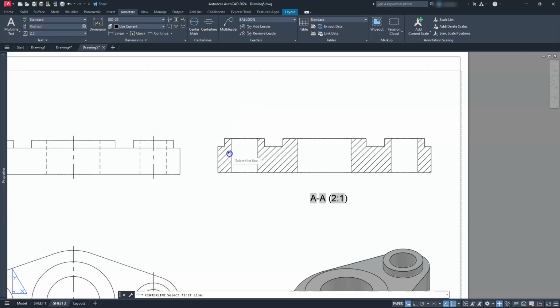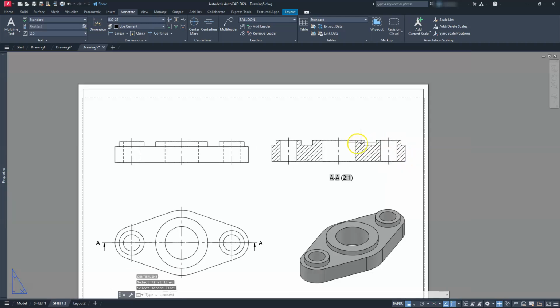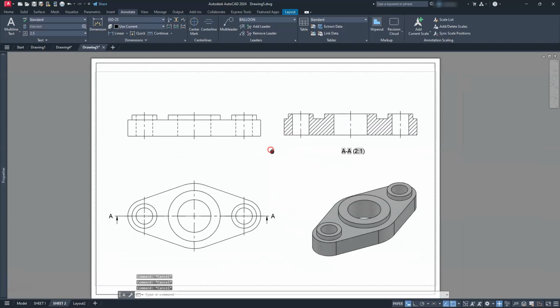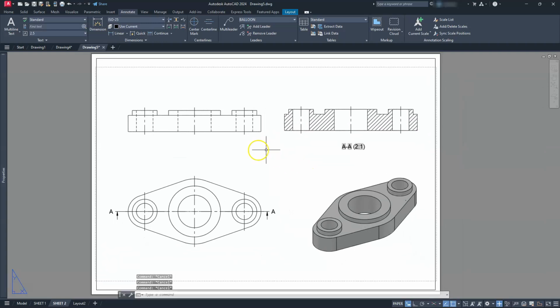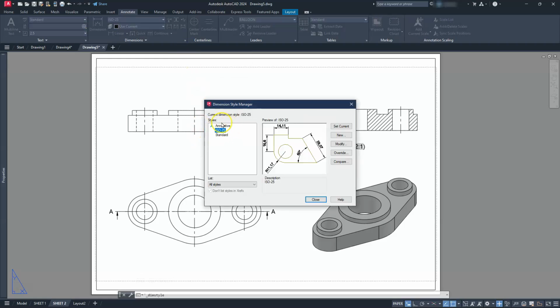But what we need to do here is just go ahead and keep putting all of these sections in. I'll just go ahead and hit the enter button as opposed to keep going up to the top. And remember that the enter button, all it does is repeat the last command. Let's go ahead and set up the dimension style though, so I will do that. Let's select this icon here. What that should open is the dialog box. We're using the ANSI standard 0.25.